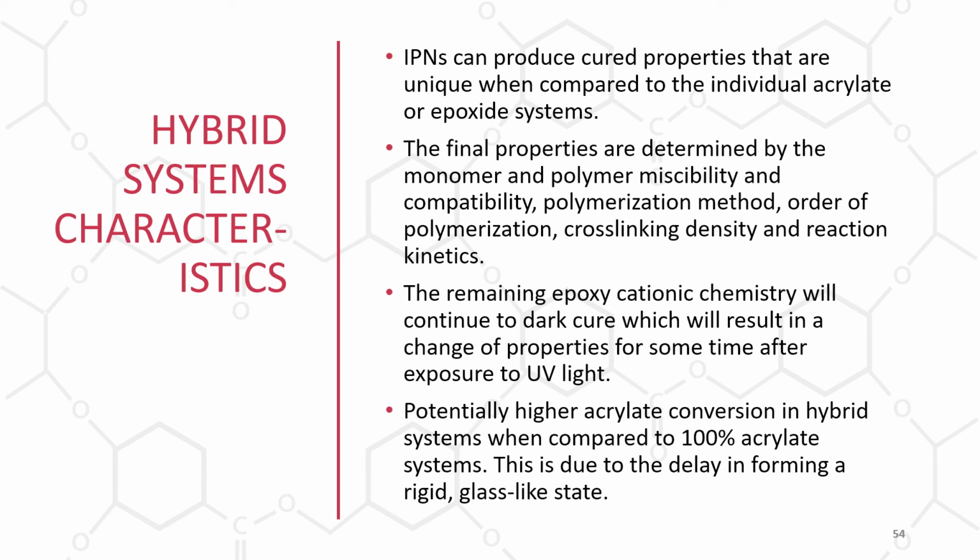And if you have planned it well, you basically drift into the properties you really need after the exposure to the UV light is finished. You can get potentially higher acrylate conversion in hybrid systems when compared to 100% acrylate systems. This is due to the delay in forming a rigid glass-like state. That delay allows more of the acrylates and methacrylates to react with the free radicals.